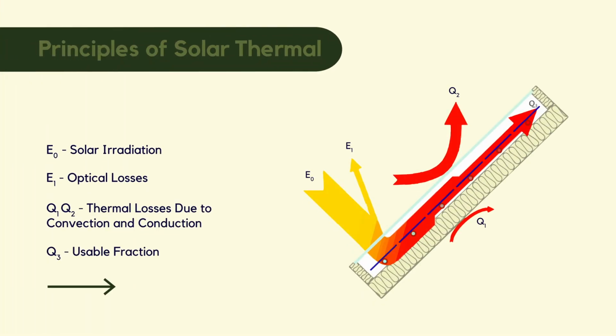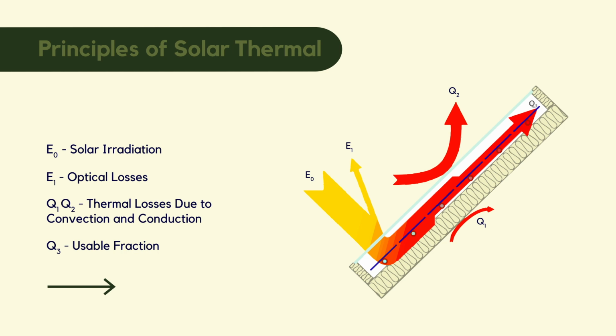The basics of solar thermal means that we have solar radiation, a certain amount coming through the atmosphere, normally 1000 watts per square meter. Part of this radiation is reflected by the cover, normally glass. Another part is conducted through the glass, and from all the radiation that passes the glass, dependent on the transmissivity coefficient of the glass, a good part of it reaches then the absorber.